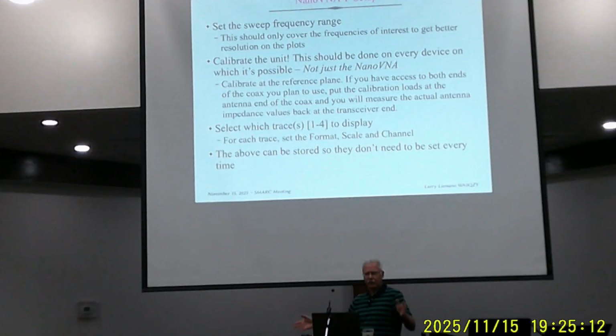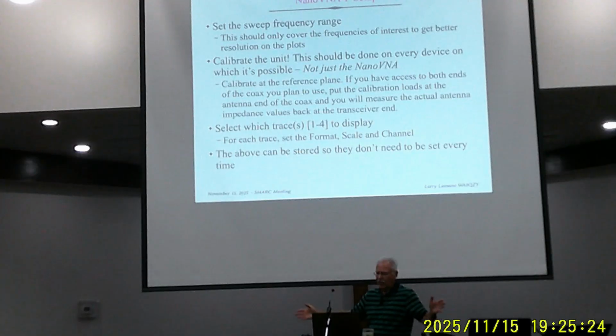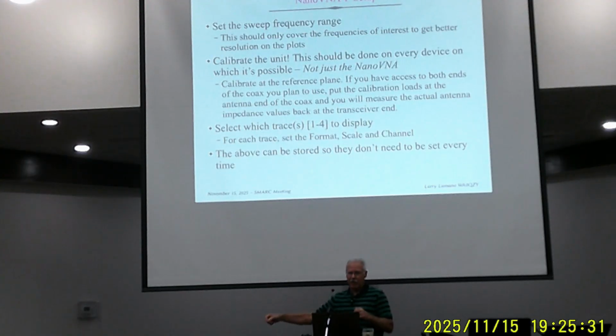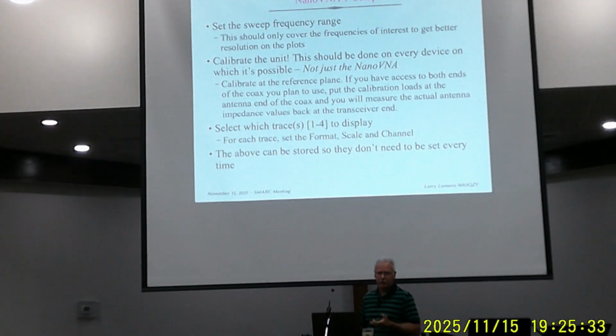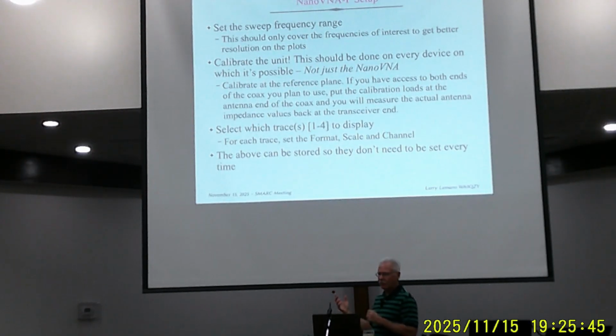But if you take 300 megahertz and 300 sample points, that's 1 megahertz per sample. So we'll be sampling at 13 megahertz, 14 megahertz, 15 megahertz, all the way up to 300. Almost all of those samples you don't care about because you're just caring about 20 meters. If you do 14 megahertz to 14.3 megahertz, now you've got 300 kilohertz divided by 300 points. That's every kilohertz. So you're going to get a sample at 14 megahertz, 14.001, 14.002. That's plenty good enough to mess around with antennas.